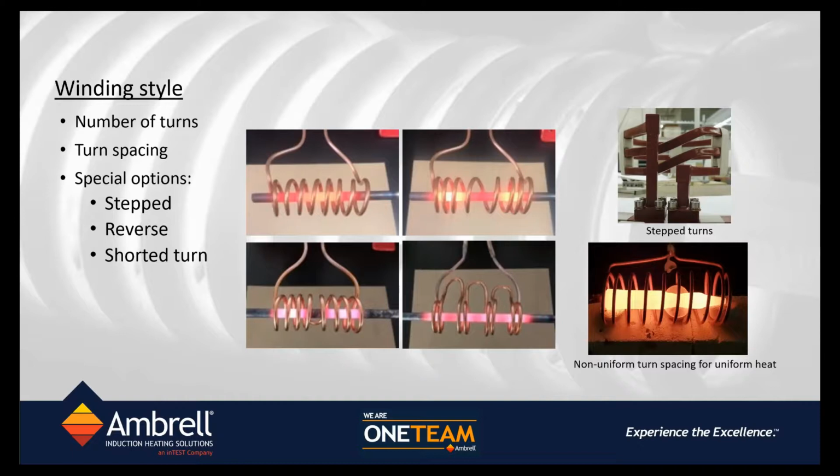The picture on the bottom right shows a very unique looking part that has intricate geometries on the same part, and then the induction heating coil has to be designed to match, to give it uniformity of heat. The picture on the top right shows a stepped induction heating coil, where the turns of the coil have a step in it to go from one turn to the next. This gives us a very nice uniform heat zone on the part.